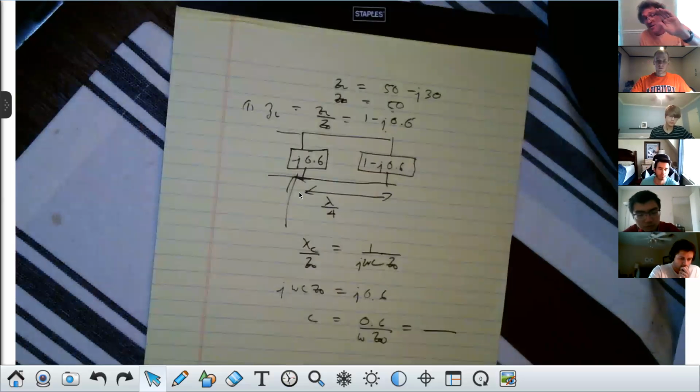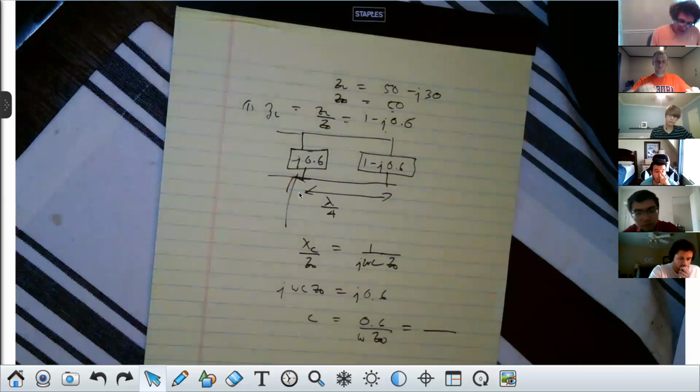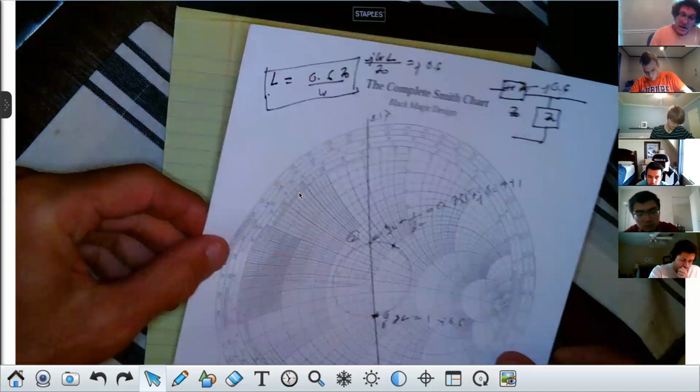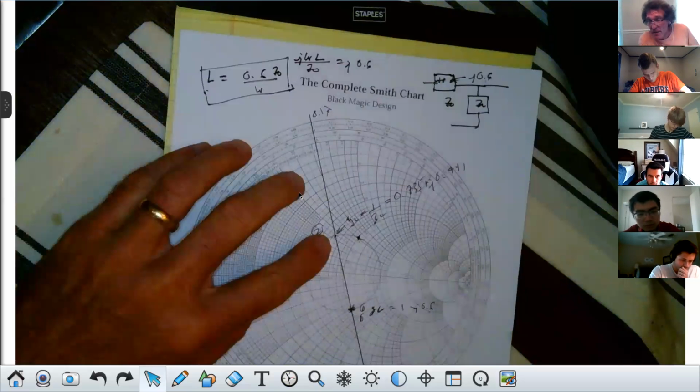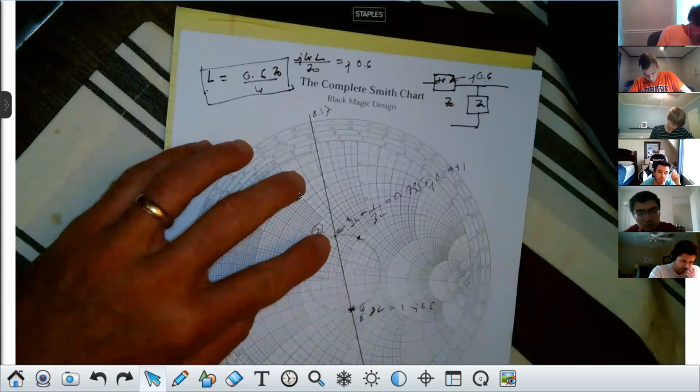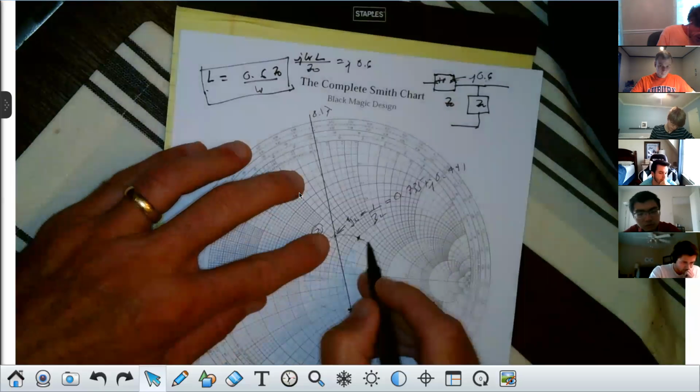Now, if I said you had to use an inductor, if I qualified that and made you use an inductor, then I'm going back to the Smith chart. And I'm going to say an inductor in parallel too, or in shunt. Follow me? So it's not in series, it's in parallel. Listen carefully. If I said that, then that means you would move to this point from here to here. Do you all see that?